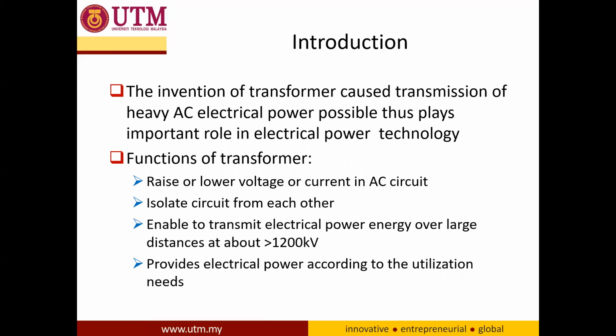Usually when we want to transmit power over a long distance, we have a lot of losses. So by using a transformer, from the generator we step up the voltage. When you step up the voltage, the current will become lower.